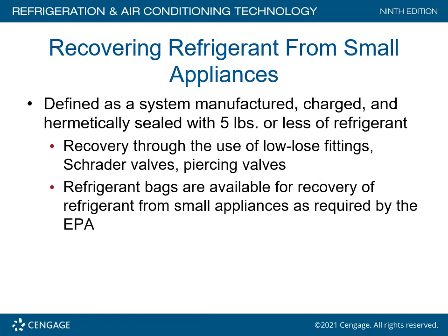Recovering refrigerant from small appliances, defined as a system manufactured, charged, and hermetically sealed with 5 pounds or less of refrigerant. Recovery is done through the use of low-loss fittings, Schrader valves, and piercing valves. Refrigerant bags are available for recovery of refrigerant from small appliances, as required by the EPA. Now, they are commonly referred to as a whirlpool bag.